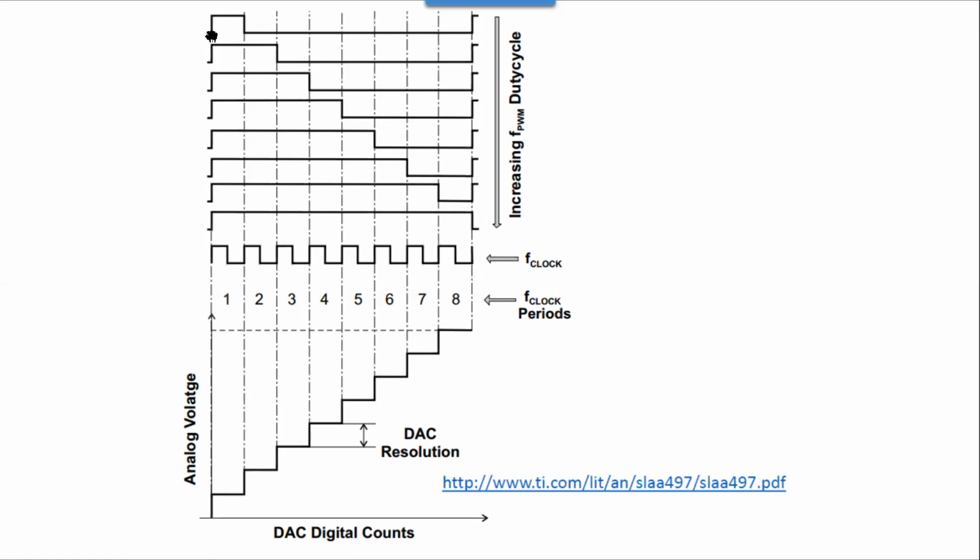But this is the system clock. You have to understand that this is a periodic signal, meaning it's not changing every clock cycle. It could go 10 clock cycles at 1/8, and then maybe 10 cycles here, 10 cycles of these periods. The advantage is you can have one output pin and effectively a low pass filter, and you've got a digital to analog converter.